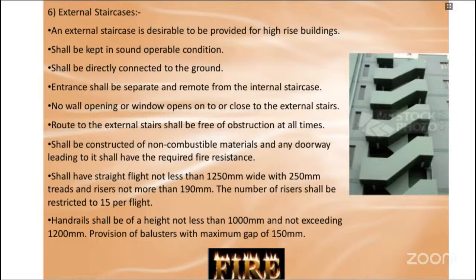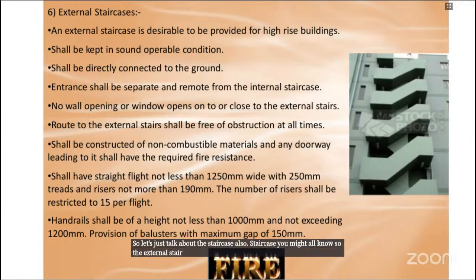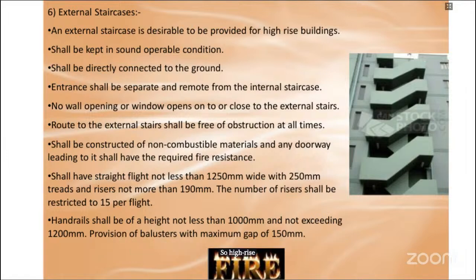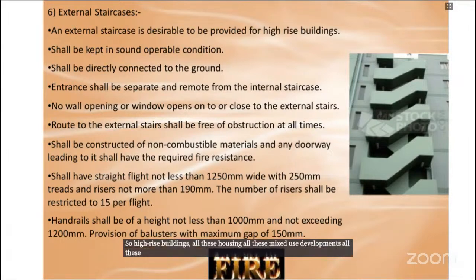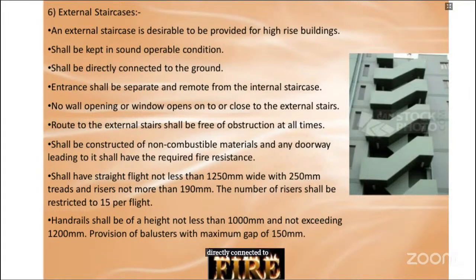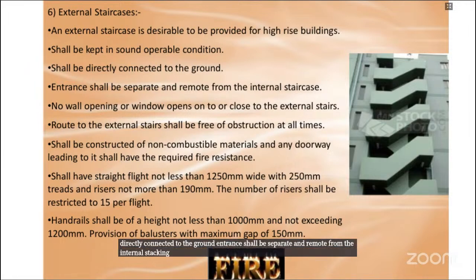So let's talk about the staircase also. Staircase, you might all know. The external staircase is desirable to be provided for high-rise buildings. So for high-rise buildings, all these housing, all these mixed-use developments, we prefer that the external staircase shall be kept in sound operable condition, directly connected to the ground. Entrance shall be separate and remote from the internal staircase. So there should be a difference in this also. We're talking about high-rise structures, skyscrapers and all.